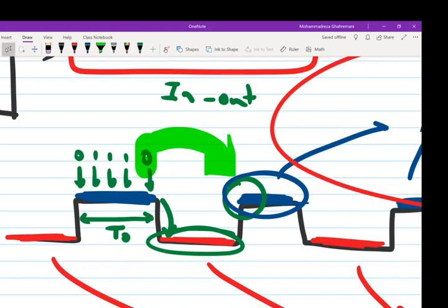As I explained, flip-flop is edge sensitive, latch is level sensitive. These two types of storage elements are related, because latches are the basic circuits from which all flip-flops are constructed.